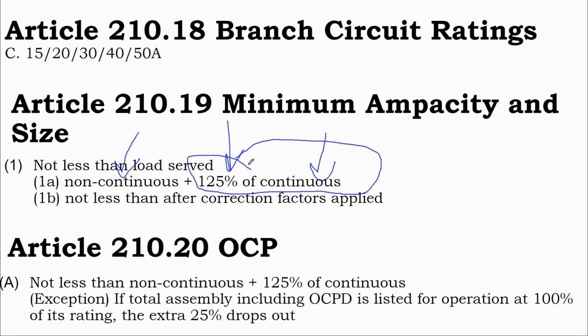Now, we're going to learn about some additional points, but basically, when you apply all the special factors on top, your starting point is assuming whatever the load is rated for. You're adding 25% on top of that to make sure that the cable is not itself going to overheat. Make sure that you're giving some headroom in that cable ampacity so that when the system is at its full load, it's not overheating.